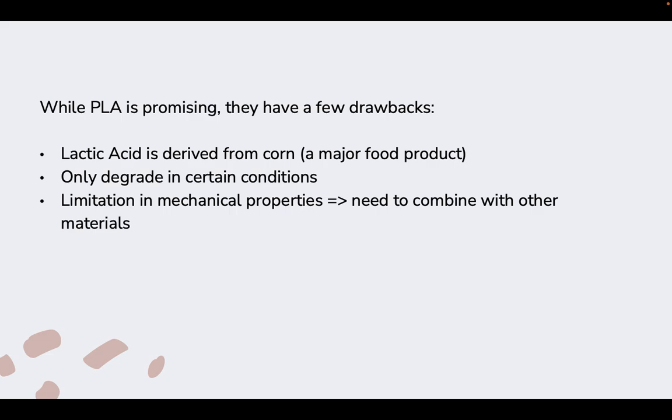And although PLA is a biodegradable polyester, it only degrades under specific conditions, and in the natural environment, it takes at least 80 years for PLA decomposition. As a result, PLA needs to be broken down via natural biological processes, such as the action of bacteria or the presence of specific enzymes. And for commercial application, in packaging for example, due to its low flexibility and poor crystallization behavior, PLA is mixed with other biodegradable plastics to enhance its flexibility.